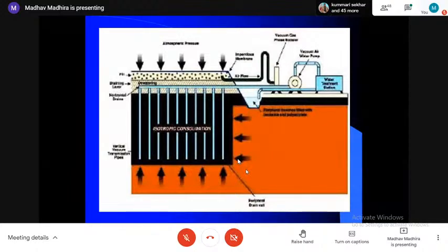All over the country we have been putting dummy load, but nowadays, with transporting, let's say I have 1 hectare, 10,000 square meters, and I had to put in 5-meter fill, it becomes 50,000 cubic meters. If a truck can transport 8 cubic meters at each trip, I need something like 6,000 truck trips. That's enormous transportation of material, fuel, pollution, carbon footprint, etc.